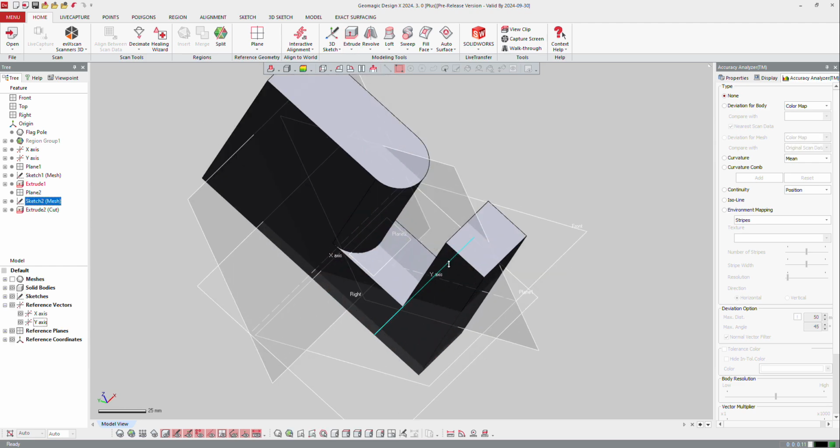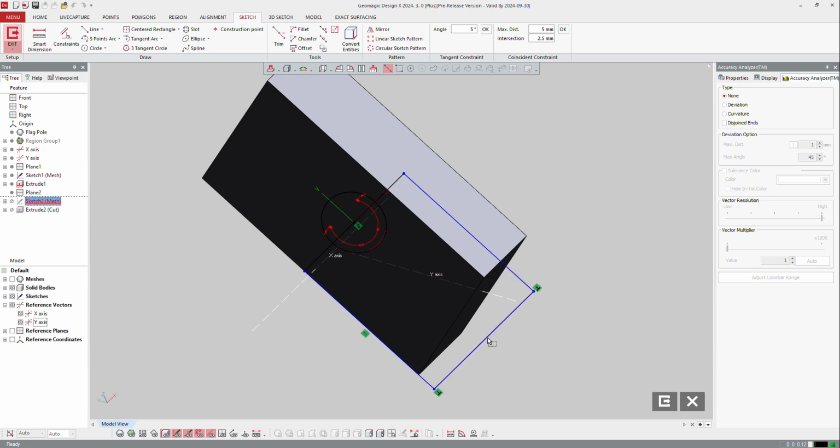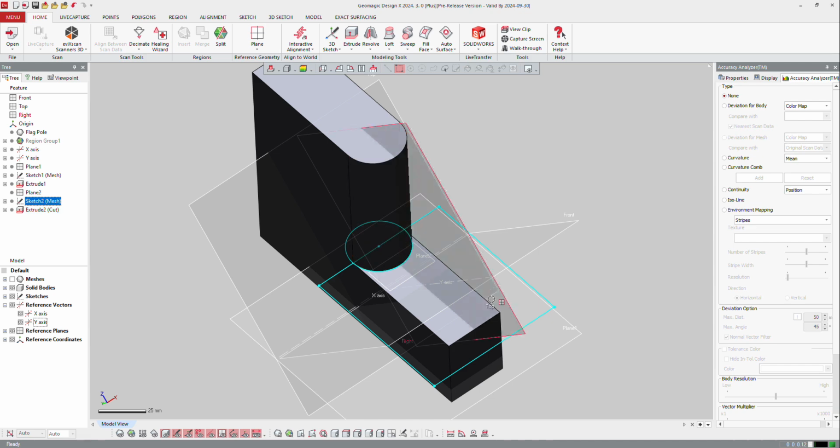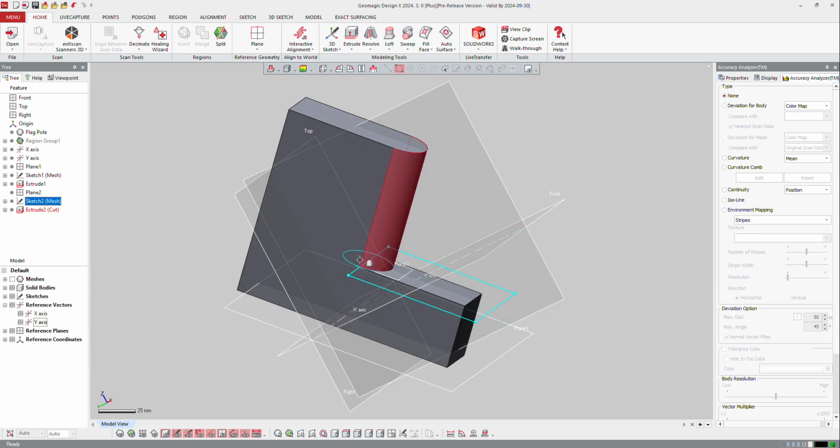What you can see, it makes a little hole inside, so you can always come back to that area and make it bigger, because my rectangle was too big, and exit. So like that, you just trim it with the extrude. Then we're going to continue with that, and I will now need to hide that and make the shape around, so around the whole part.